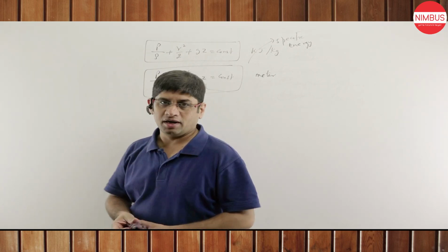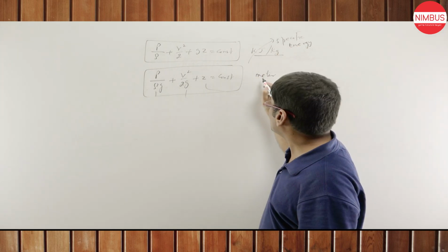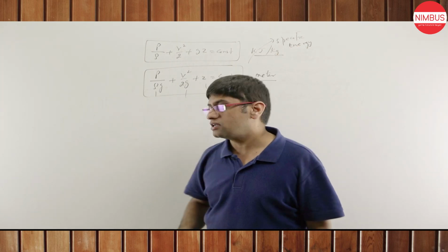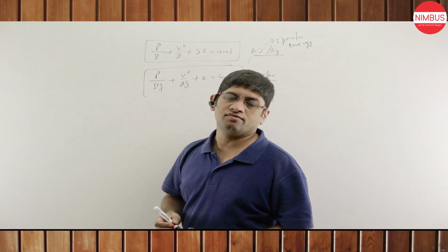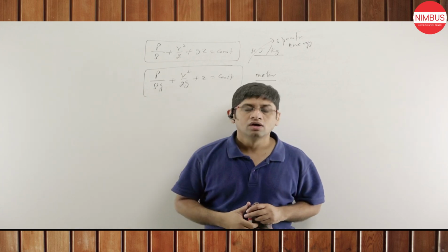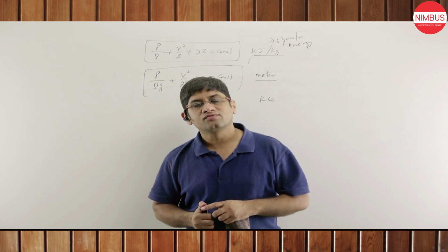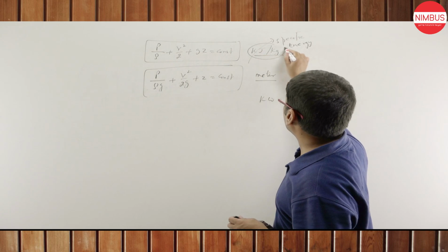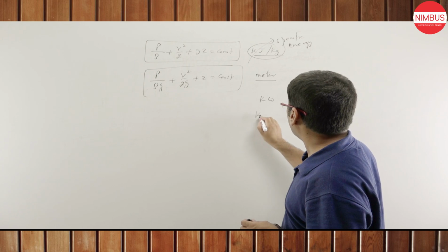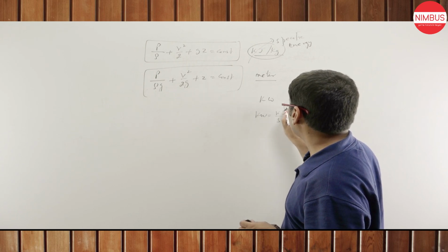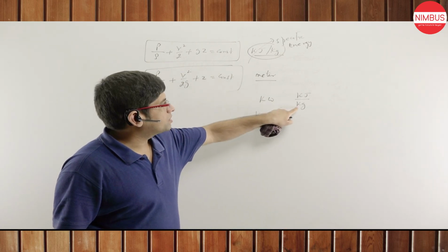Now I come to third part. He is going to ask you, do not write Bernoulli equation in specific energy term. Do not write in terms of head. Write it in terms of power, kilowatt. Because I want to know what is the fluid power I have. What is the fluid power? Now, can you tell me what should I do if I want to get power from energy? This is the energy, kilojoule. This is kilojoule per kg. And you know what is kilowatt? Kilowatt is kilojoule per second. So what should I do to this kilojoule per kg so that it becomes kilojoule per second?